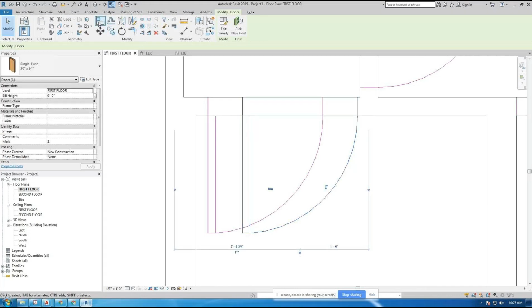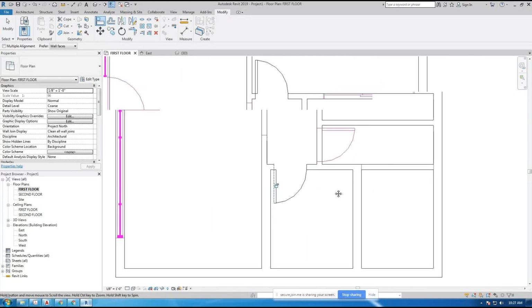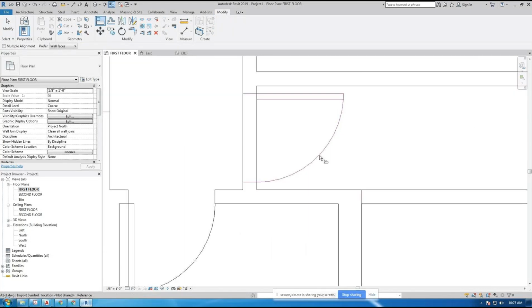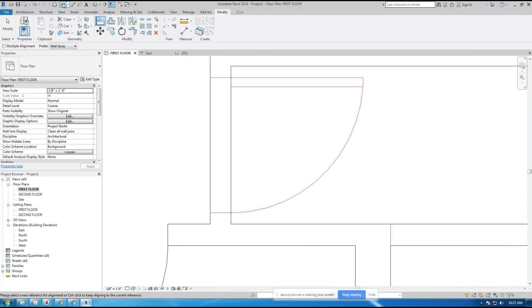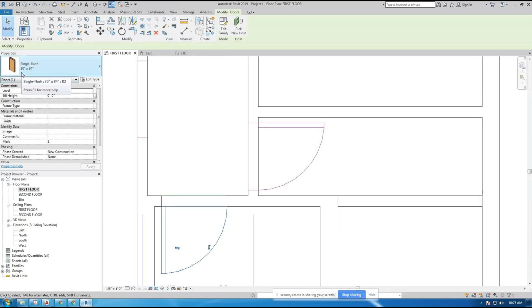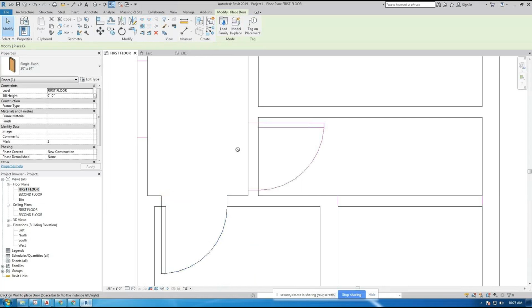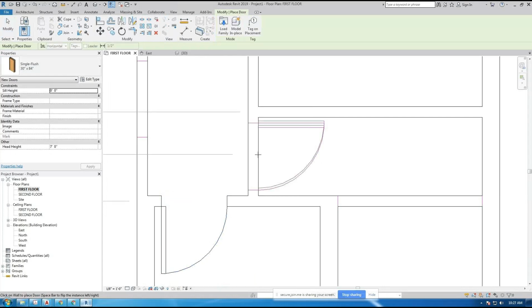This time, instead of move, I'll use align. Align command means align. Where do I want to go? I want to go to this edge. Okay, what's going to go there? This edge of the door. Click, the door moves over. Done. Very quick and easy. How big is this door? I have no idea. Tape measure from here to here. That looks like a 30-inch door. Okay, fine. How big is this door? Well, that's a 30-inch door also. Therefore, right-click, create a similar door right here.